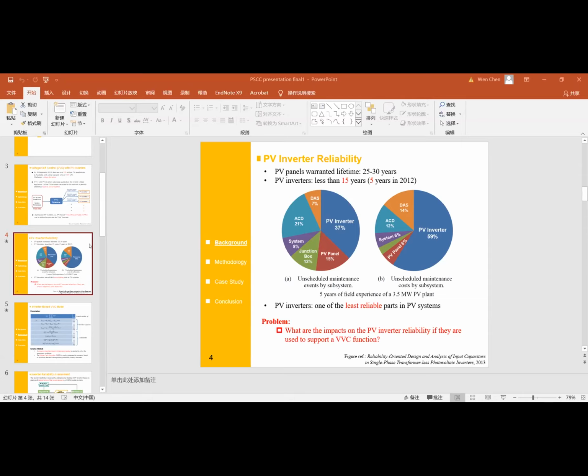But the point is, the use of reactive power can also help mitigate the active power fluctuation, and this fluctuation is one key parameter for the inverter lifetime. And its impact, I think, is much more than the junction temperature mean value. That's my opinion. Thank you. Any further questions?